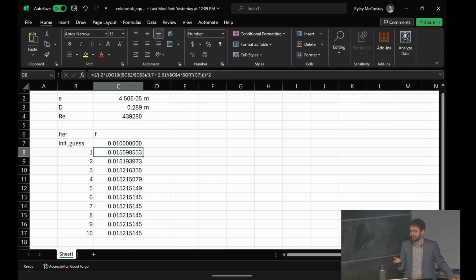I'd recommend going through that because in your tutorial this Thursday, the friction factor calculation is definitely a little complicated, but it's not really the key concept here. The key concept is about major losses in pipes. So for example, for a fixed volumetric flow rate, when your diameter changes, everything changes because your Reynolds number changes, your friction factor changes, so the pressure drop changes. There's a lot of different effects there. So in the tutorial on Thursday, we're going to explore the effect of these different variables. So it's good just to have a base knowledge of how to calculate the friction factor.